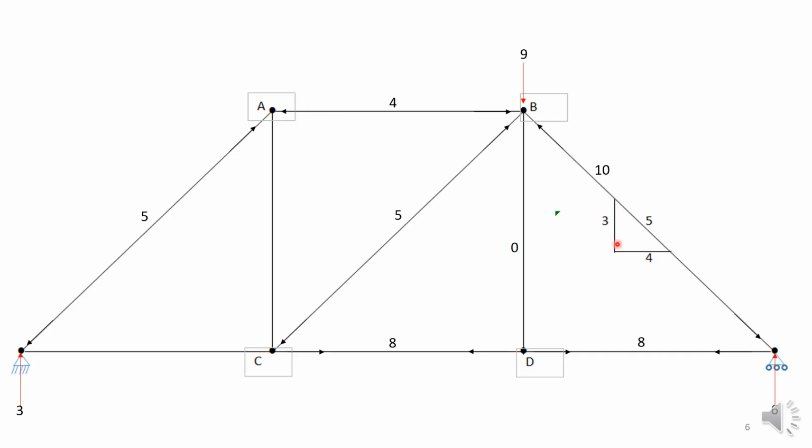Okay, we are using these proportions also. And you can look at the vertical components at A. These must be in equilibrium. You have an upward push from this sloping member. This has to be balanced by a tensile force in this member AC of 3 units. You can go over your basic statics and just verify what I'm doing here is correct.